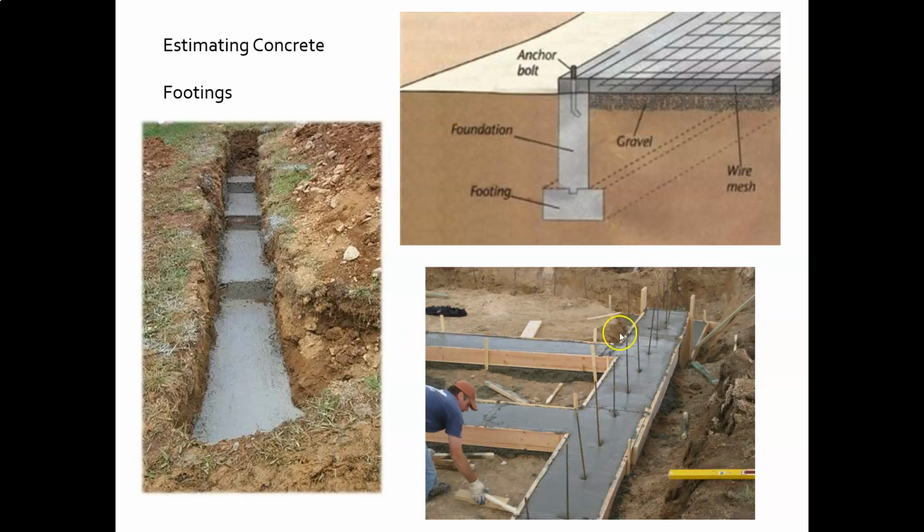And one important thing that we will have to do, and this is a good place to point it out, is when we calculate the linear feet of this run, for instance, then this one is coming into it. We don't want to double count this area, that area, or this area. Usually in architecture plans, when we're given dimensions, they're to the outside of the footing.